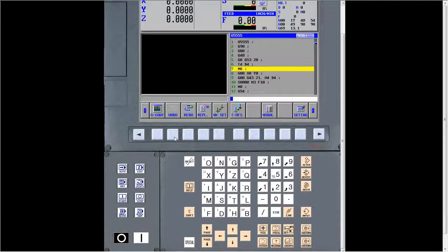So how about engraving on that same kind of machine? Yes, engraving is totally possible. Obviously, if you have a live tool lathe, there's different configurations of live tool lathes. You can have one where there's 3 axes, where you have X, Z, and then the C axis on the spindle, where you're going to be doing polar coordinate programming. So yes, you can do engraving that way. And then you can have a mill turn machine where it's got a Y-axis. And then it's going to be more like a mill lathe. So you can do it both ways. But yes, you can do engraving also.